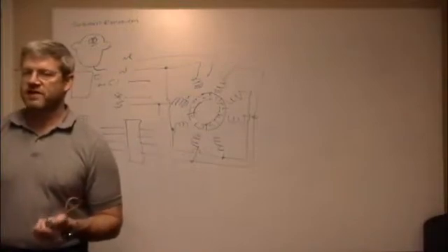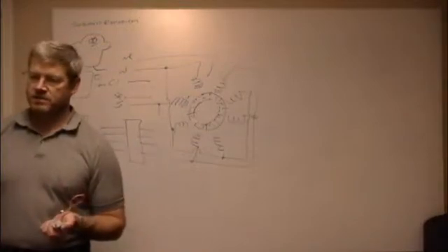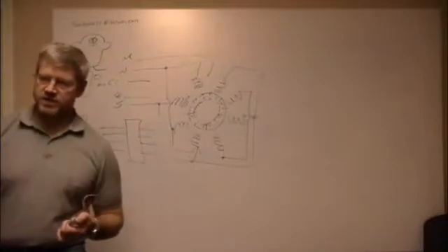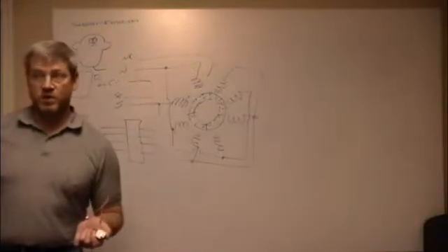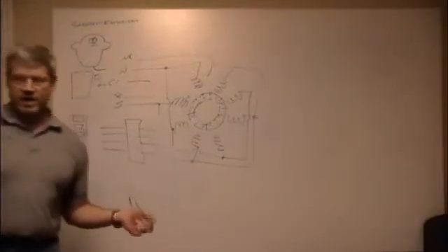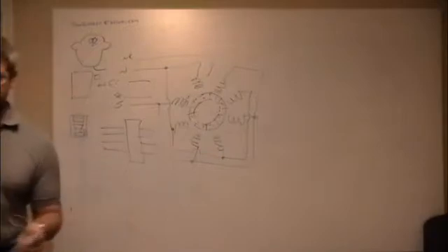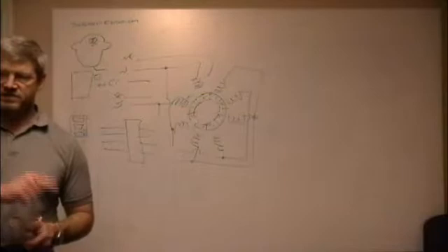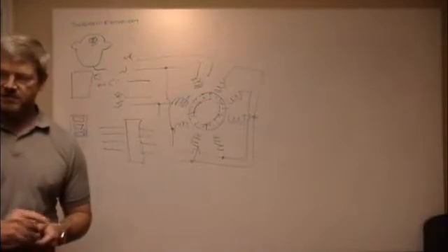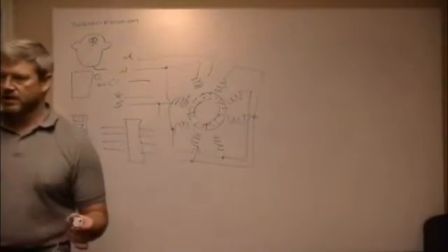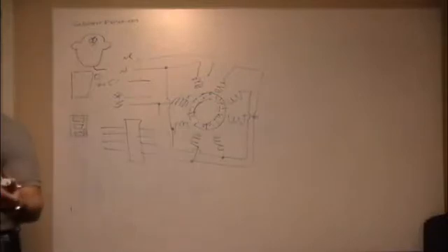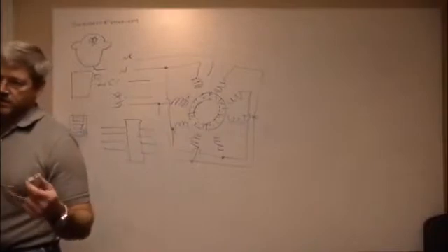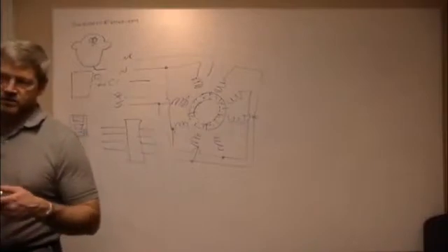The servo has a feedback of where it is internally, unless you have a big system where you're controlling it. So you can tell it to go there, and you know that it's going to go somewhere close to there. But then, no matter what happens, it's going to drive and try and keep itself there. Whereas with a stepper, I can say step, step, step, step, and I can count 50 steps, and I know that you should be at step 50 now. And I can go away, and it will lock, if I've got the current turned on. You have to be able to overcome that current and torque to be able to move it.